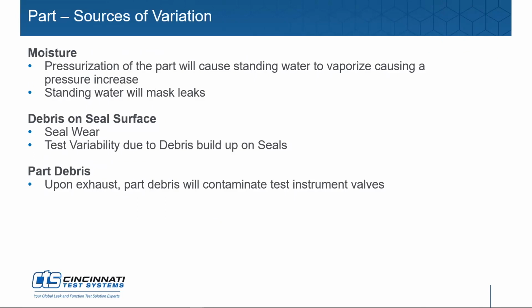Other variation that you see: moisture. Standing water on a part will actually cause 2 issues. One, it can mask a leak. Like we said earlier, certain hole sizes have flow rates of air 80 times that of water, and a hole will actually clog at a certain rate with water. If you have standing water on your part, you run the risk of clogging a hole or masking a leak.